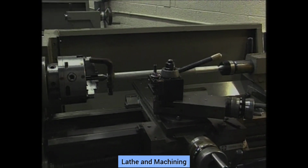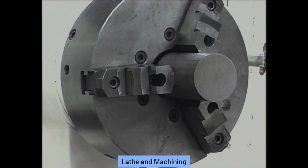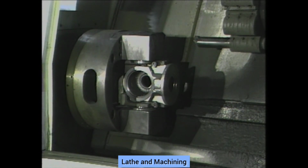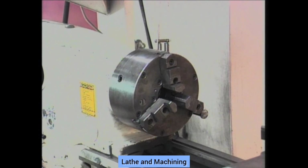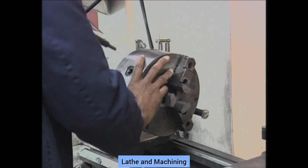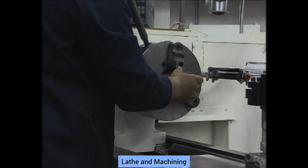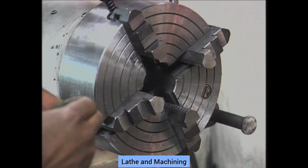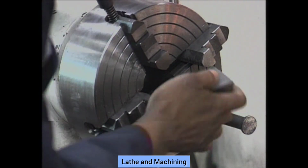Work is held at both ends between centers, which are pointed conical pins, or held at one end by a chuck, a collet, or, if an unusual shape, by a fixture. Chucks fit on the spindle nose of the lathe and hold short, large diameter work. There are many types of chucks, and they are either manually or power operated. 3-jaw universal chucks are the most common. All 3 jaws move in tandem to grab a round workpiece, center it, and grip it. Irregularly shaped workpieces may be held in 4-jaw chucks, in which the jaws adjust independently.